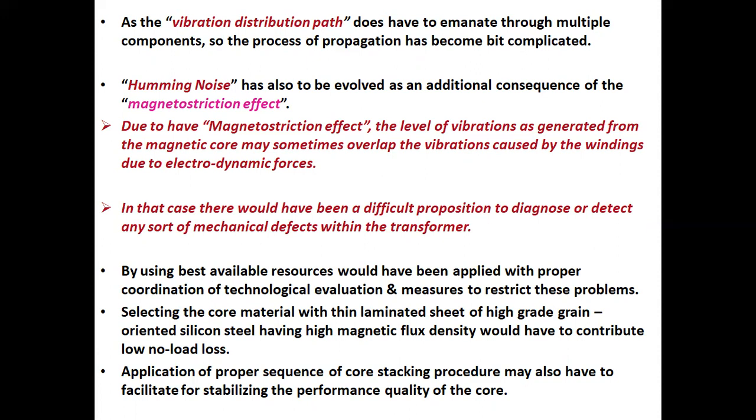Due to the magnetostriction effect, the level of vibrations generated from the magnetic core may sometimes overlap the vibrations caused by the windings due to electrodynamic forces. In that case, there is a different proposition to diagnose or detect any sort of mechanical defects within the transformer. The best available resources should be applied with proper coordination of technological evolution and measures to restrict these problems.